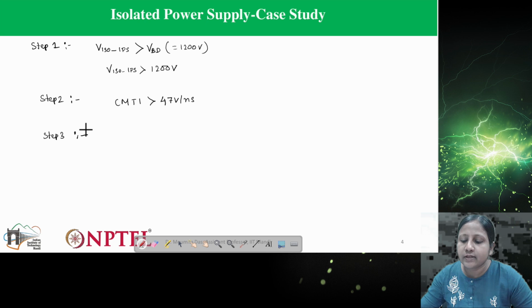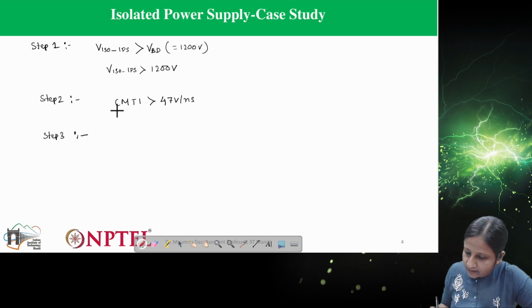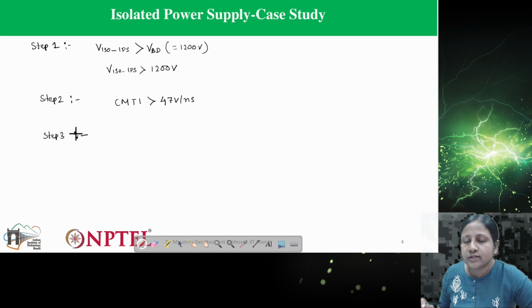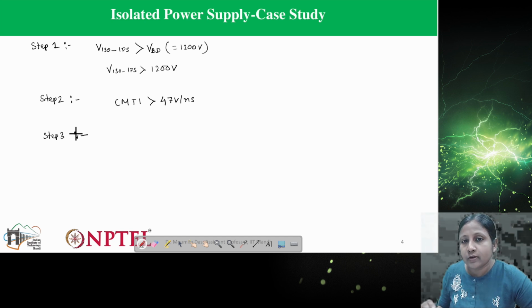it is actually the same. Basically, for the isolated power supply, we have to consider the required voltages. These required voltages will be different, because this voltage will go to the gate drive, and the gate drive will amplify the voltage level of the microcontroller based on the power supply coming from the isolated power supply.